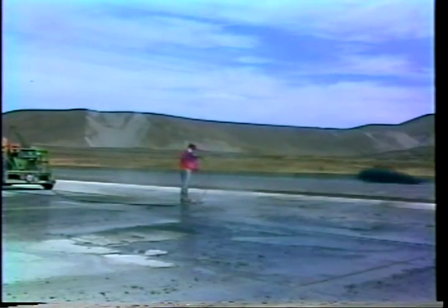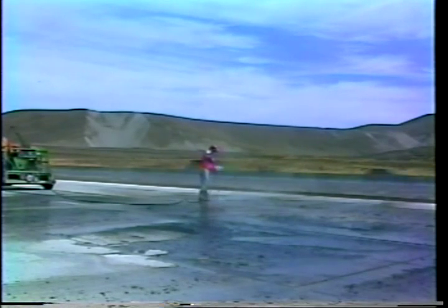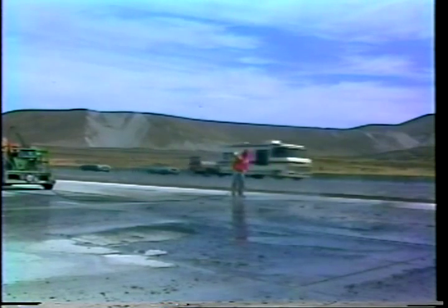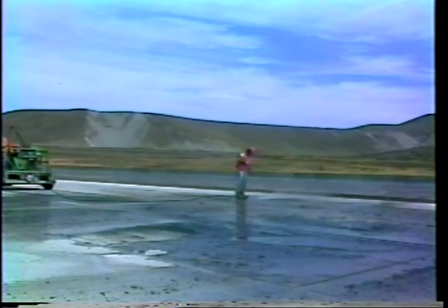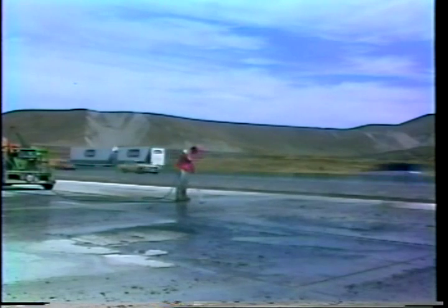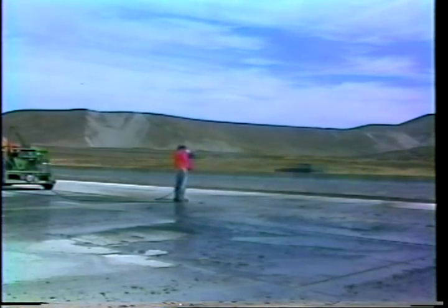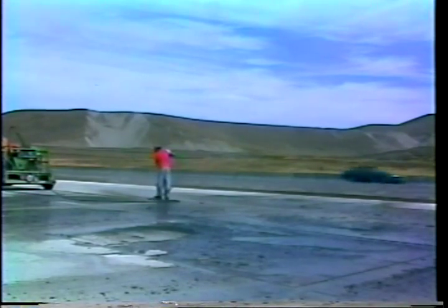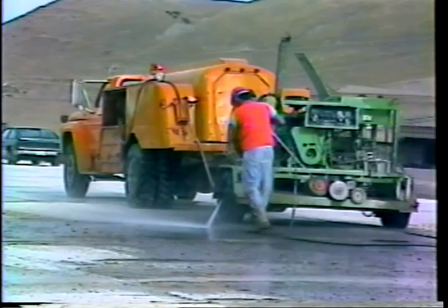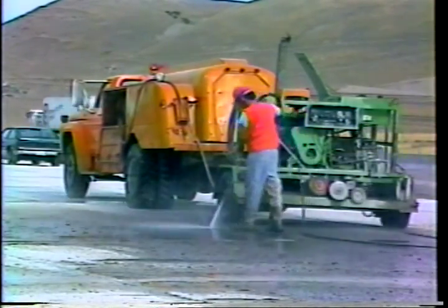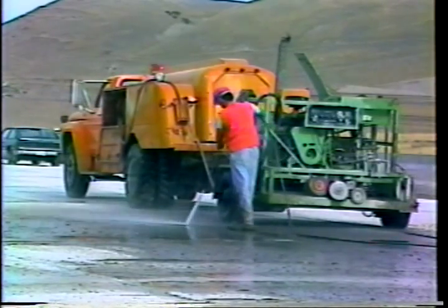The third option is water blasting. Here, water pressures of up to 30,000 psi are used to remove the deteriorated concrete. This method has 2 advantages. First, all the material can be removed without the danger of damaging the surrounding concrete. And second, water blasting leaves a clean-cut surface with excellent roughness and angularity, which will promote bonding with the repair material. There is, however, one disadvantage. Because of the tremendous water pressure, it's difficult to control the depth of removal.